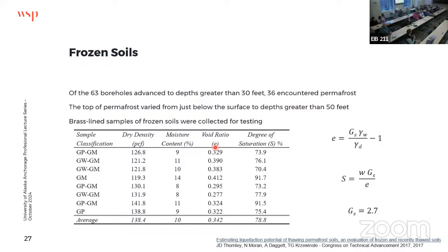I have more of a comment. I did my thesis on the Corral site on Farmer's Loop. We were doing our drilling for that site, the top like 20 feet of that where we were at, where our piles were, it was thawed. And when we drove our split spoon down in there, you can basically just see the thawed ice lenses in that silt. They're still there. So it's just extremely young, super unconsolidated deposit. Yeah, liquefied for sure. And then ice content below, so it's, I think, over 100% in some places. So it's pretty high.